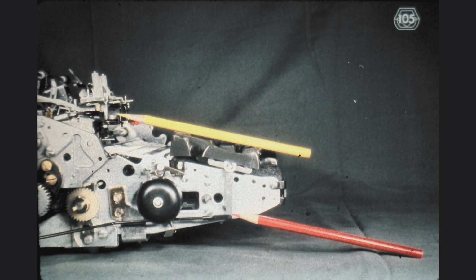Finally, we use the clevis indicated by the red pencil to adjust the position of the tabulation set and clear key. Notice also the yellow pencil on the key tops. It indicates the slope of the keyboard. The tab set and clear key top should follow the same slope when the machine is at rest. Again, check your machine for these requirements.